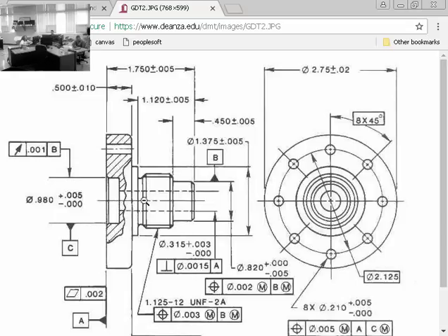Watch out for that. Normally when it's attached to a surface, everything's hunky-dory. So for example, A down here is attached to this surface, so it's the back of the part. So they're measuring from the back of the part out. That'll make sense. And you also see that this one, in fact, may also be a diameter. Even though I said it was the surface, it's actually the center line of this cylinder. So they're tricky sometimes with how these datum symbols are placed.